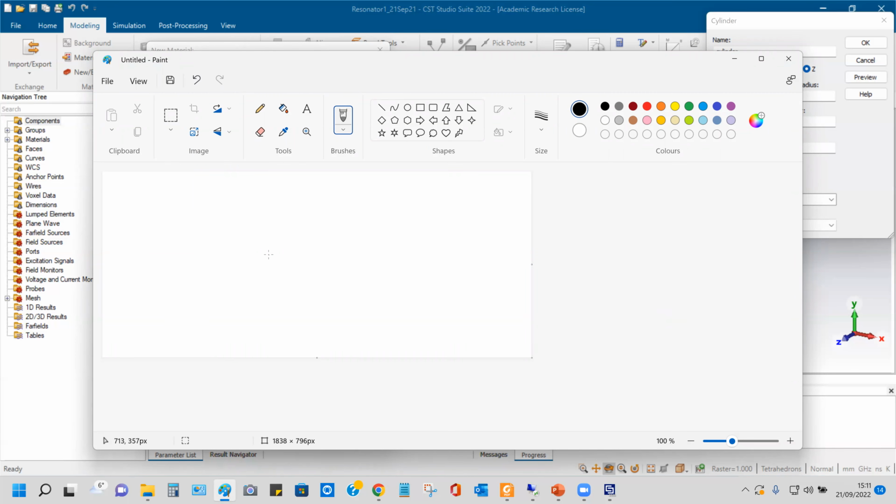Okay, so usually the plots will be something like this. Here it will be frequency. Then here it will be epsilon or tan delta, basically tan delta. This is loss tangent. For example, they will measure it from 0 to 18 GHz. Then the value may be like this.